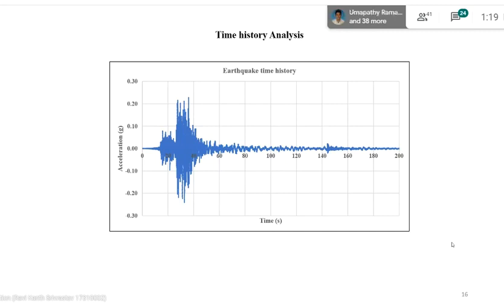At any instant of time, this force is changing, and if the structure has gone into the non-linear range, what happens is our initial structure was something, but when we have applied some force to that structure, at some instant of time, the building will deform, and it will deform permanently. Once it deforms permanently, and when some additional force is applied, the analysis will be carried out for the deformed shape of the building, not the initial shape, right?